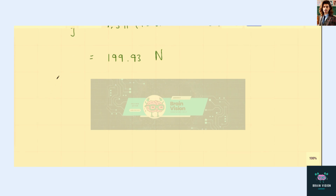Now, using the results for Fx and Fy and referring back to our free body diagram, we know that the sum of the forces along the x direction must equal 0. And so 82.81 minus the tension T in the horizontal direction must equal 0.